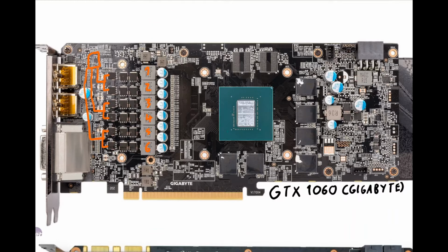You see it a lot on motherboards, and you can also see it on high-end graphics cards actually. My RTX 2080 Ti, which is a Gigabyte Aorus Extreme card, has 16 phases worth of components on there, but the PWM controller on it, which is the UP9512, can actually only support 8 phases, and there are no doublers on that card. So these 16 phases are actually 8, and there's just one PWM signal going into 2 physical phases. So it's actually an 8 phase.